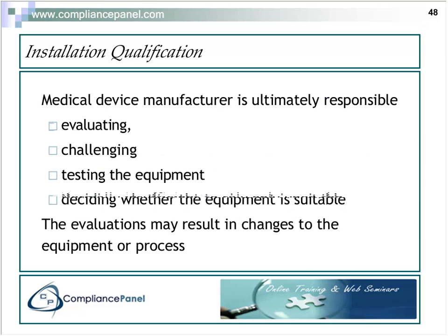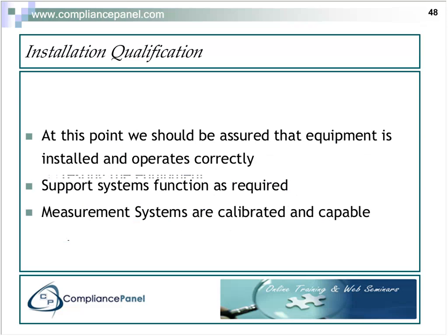We are ultimately responsible as a medical device manufacturer for evaluating the IQ, challenging the equipment, that is testing it over a wide range of its capabilities, and deciding whether the equipment is suitable or not. We may have to make some changes to the equipment or the process as a result of this. So at the end of IQ, we need to make sure that the equipment is installed and operates correctly and that the support systems function as required.